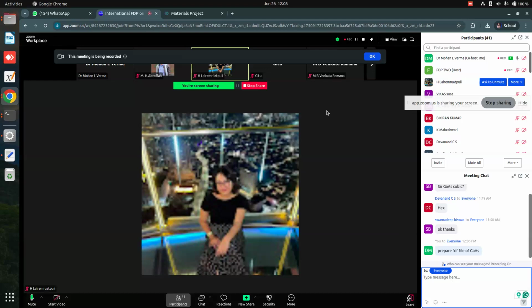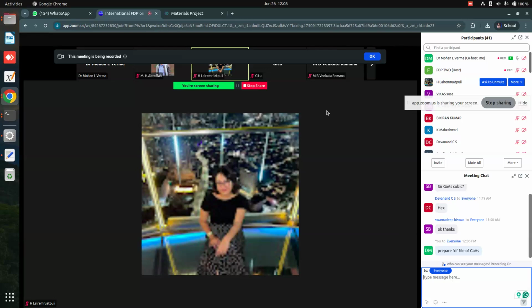So this is the method of FDF file generation, and I've shared that FDF file as a template to you for your help. What you have to do is just download the CIF file and convert it into an FDF file by using GDIS. But GDIS gives so many extra lines in the generated FDF file. So you just have to delete all extra lines after the coordinates and paste the lines from my template, and then your file will be ready. And at the top, you have to mention the system name also. So this is the FDF file.